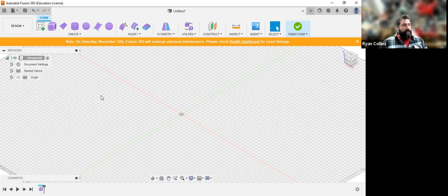But main thing is, I want to talk about how does this work? Now, there's a couple different types of modeling. We're not really going to talk about the first, which a lot of other programs use, which is called NURBS modeling, N-U-R-B-S. It's non-uniform rational B-splines. Basically, it's three-dimensional spline tools. Works off of control points, so the points that we had been drawing to create a spline. That's how those work. T-splines is what Fusion uses. It's very much the same type. It's just slightly different. Whereas the other is more of like a mesh, T-splines are more of a